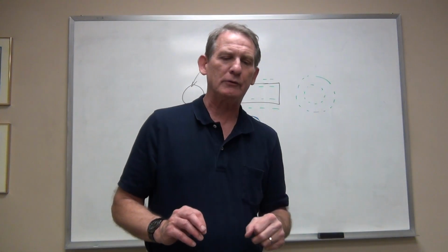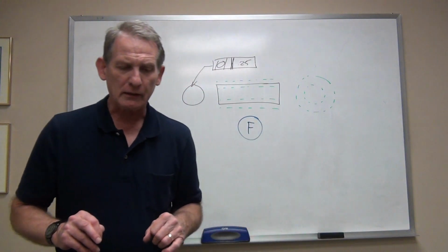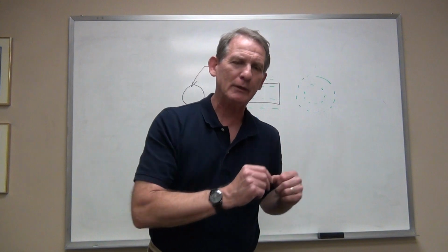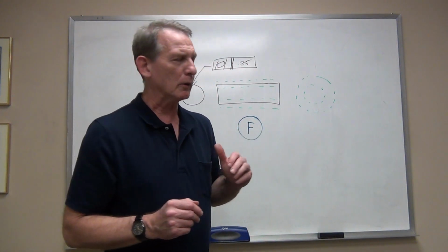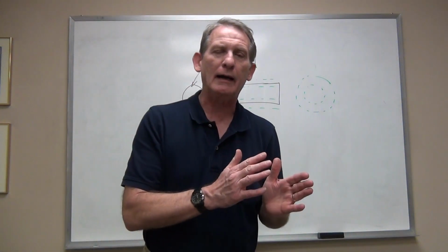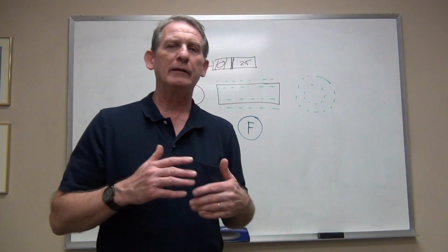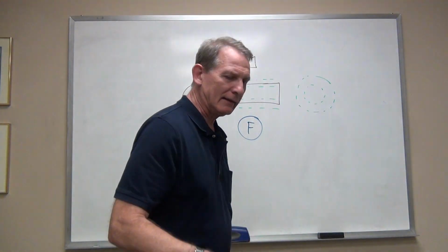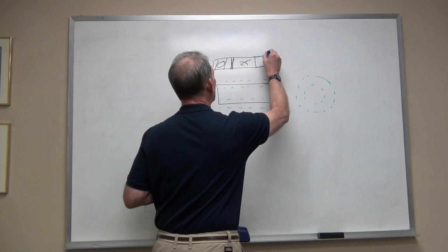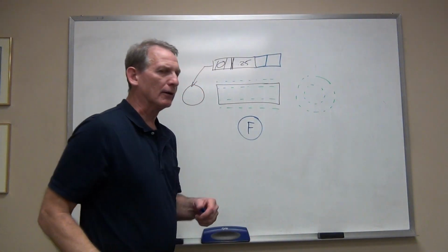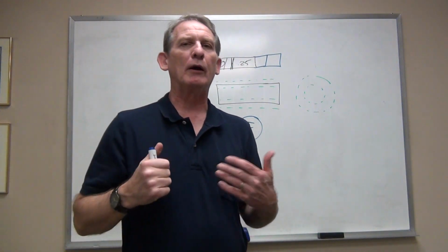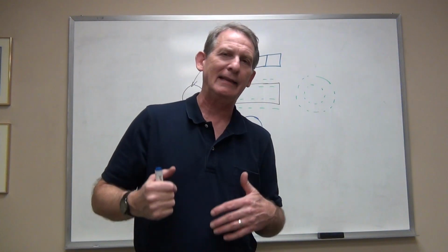But we're going to move on to tolerances of orientation. Tolerances of orientation are just another level, a little bit more complicated. While we were using the feature control frames for form, there's only those two blocks. In orientation, we are always going to add at least one, and sometimes more, box here to use as a reference point, and that reference point is called a datum.